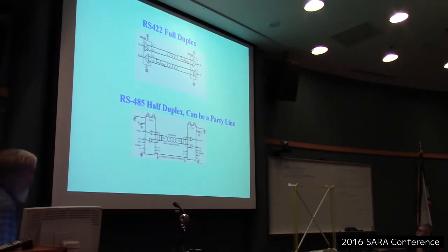They're useful. By the way, I've also used RS-422 and 485 drivers just for driving things like phase switch signals for a phase switch interferometer, control signals. Even though they're intended for serial communications, just a 1-bit control signal could very easily go through one of those driver receiver pairs. And again, it breaks ground loops.